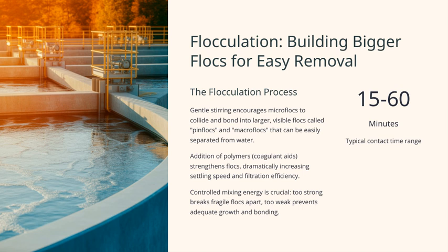Adding polymers, or coagulant aids, plays a significant role as well. These substances strengthen the flocs, which dramatically increases the speed at which they settle and improves the overall efficiency of filtration. However, controlling the mixing energy is essential. If the stirring is too vigorous, it can break fragile flocs apart, undoing the process. On the other hand, if the mixing is too gentle, it might not promote enough bonding and growth of the flocs. Typically, the contact time for this process ranges from 15 to 60 minutes. This window allows sufficient time for the flocs to form and grow, ensuring optimal removal of contaminants.